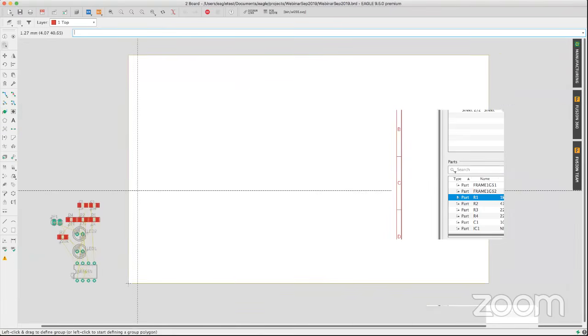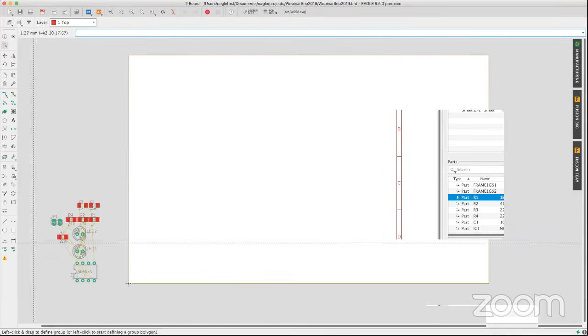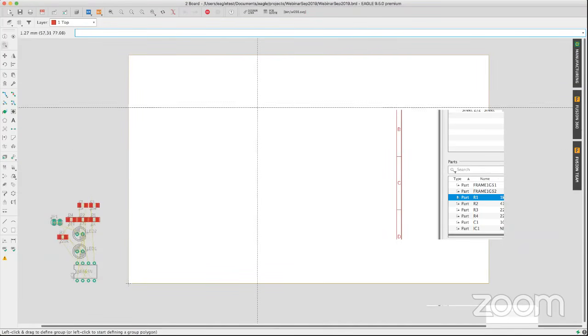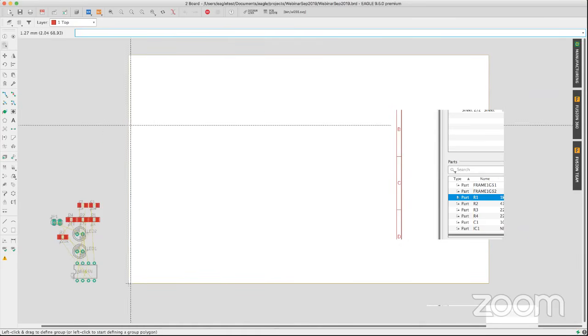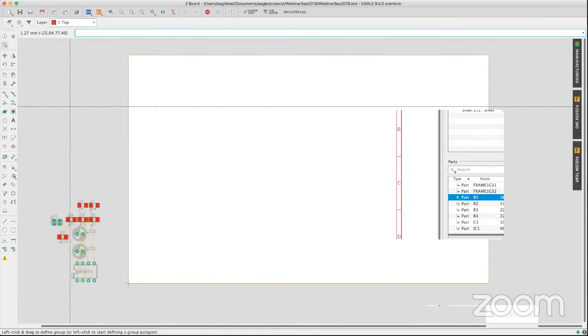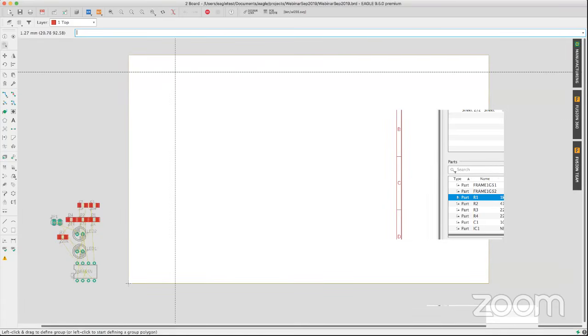And as you can see, it brought all the assets from the schematic over to the left-hand side of an empty board editor. This is my board space, and what you see in the foreground here is outside my board space. That's the difference. If you plan to have an electromechanical workflow, you have to make sure that your board outline is sealed. That way, when you move from Eagle to Fusion 360 and have that bidirectional electromechanical workflow going, Fusion can recognize that there's actually an outline.